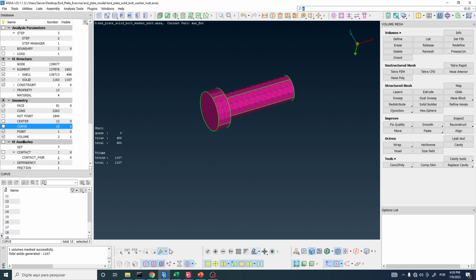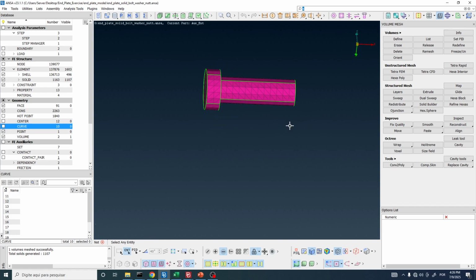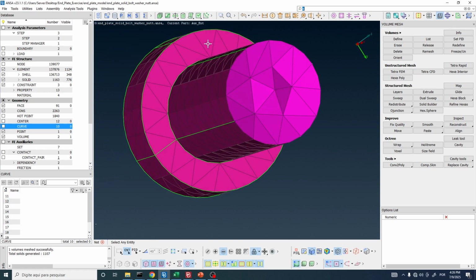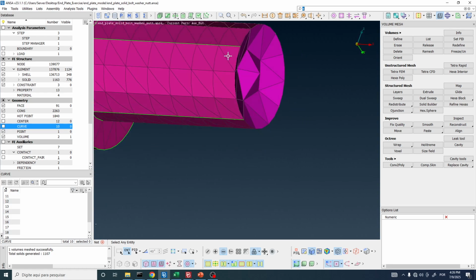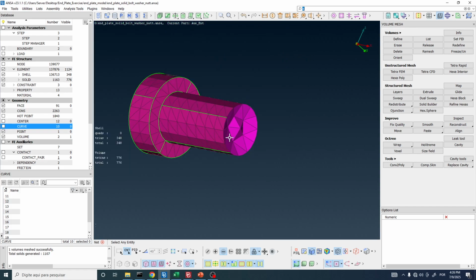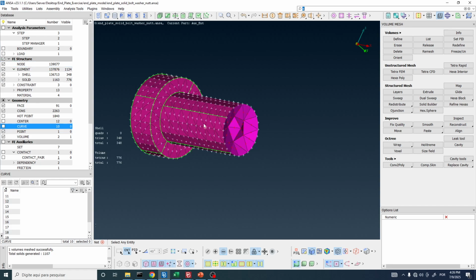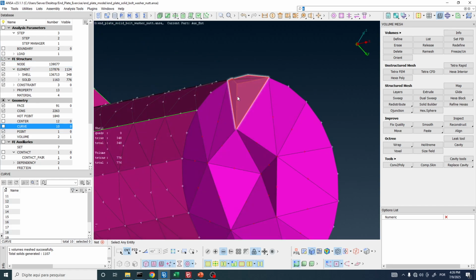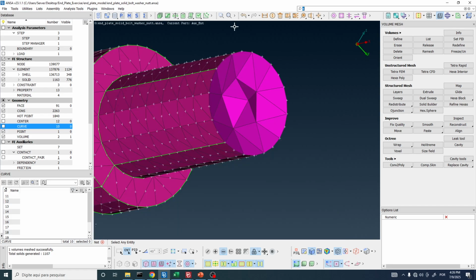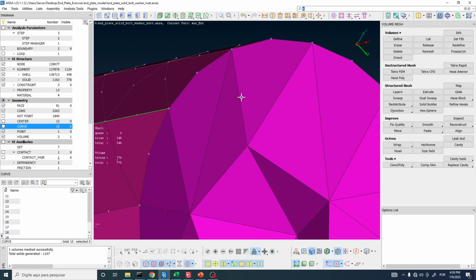Right, let me lock this view, clicking here. Let me use the node function, entity selection mode, get a view like this, use the left mouse button to create a cut, and then you see that we have these solid elements inside. Now, if we activate the visualization of nodes by checking this box, zoom in, you see that for these solid elements, we have the mid-side nodes.